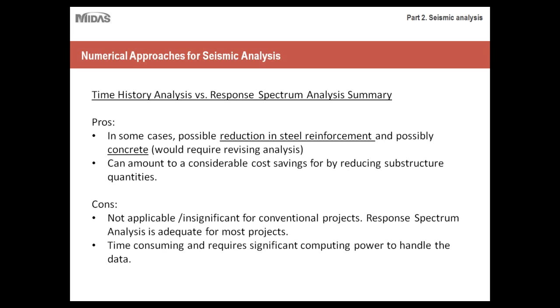So if you decide to go with a time history analysis, just make sure first and foremost, one, that it's worth the investment, and two, that you're properly equipped to handle it. If you don't have a numerical modeling program, it's really not realistic to do time history analysis because all engineers, especially out on the West Coast, have numerical modeling programs that are very specific to seismic analysis to help them save on the time they invest, because time history analysis is just so prevalent there. So those are the two things to keep in mind. One, make sure that you actually need it, and two, make sure that you're equipped to handle it if you do.